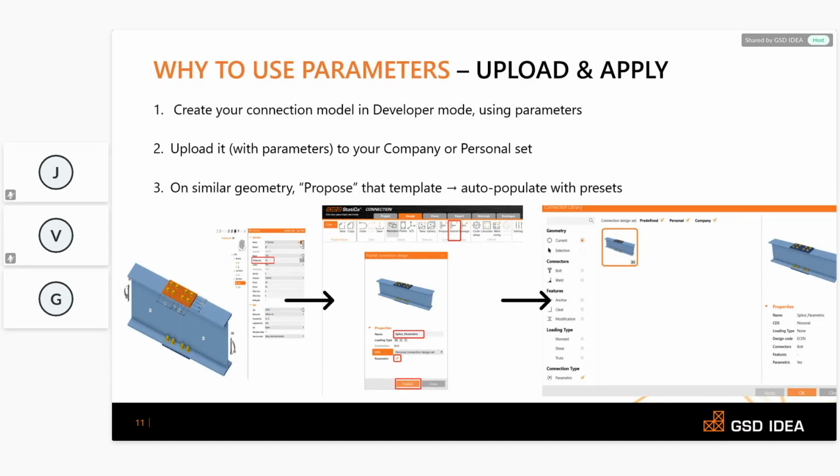For this, all we have to do is just select the template, and the software would auto-populate the model using the saved template. The geometry operations and all the logic, whichever we have inputted in the parent template, are filled in quickly. You just enter the new parameter values like updated dimensions, etc., and you're ready to check the design. Now, this saves a massive amount of time, as I've already mentioned, especially for repeated joint types like beam to column or splice connections.